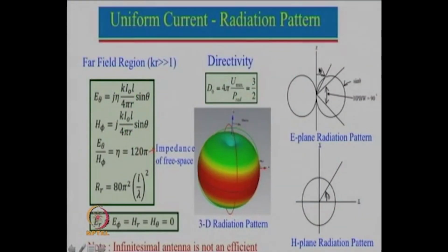So, here is the dipole antenna. You can imagine a pen over here. We see the maximum intensity, or maximum radiation, in this direction, and then as we move along, we hardly see anything. So, this is the 0 radiation on this side, and then this is repeated on this side. This is also known as a figure of 8.